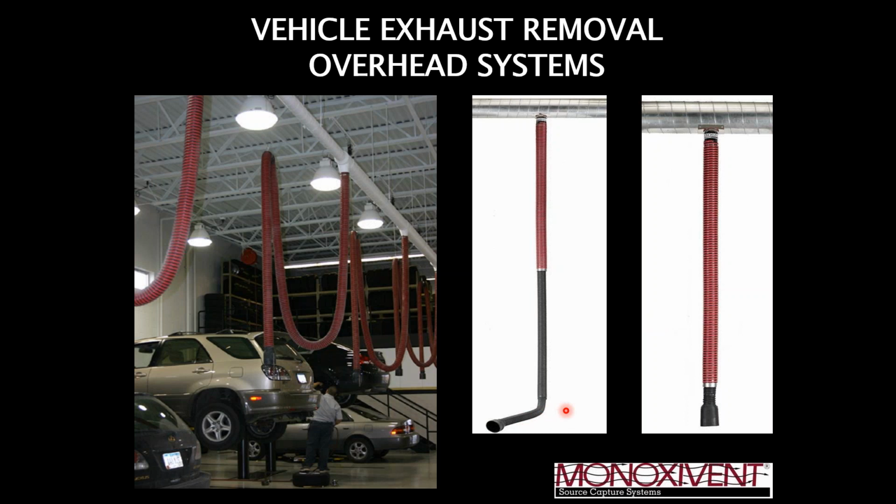What some people would perceive to be a negative is because my lowest section is 3-inch diameter, I can't do more than about 150 CFM through that. And what that means to you is that's strictly for automobiles only, and only in a tune-up or idling type application. But if that's your application, this is a very inexpensive solution.